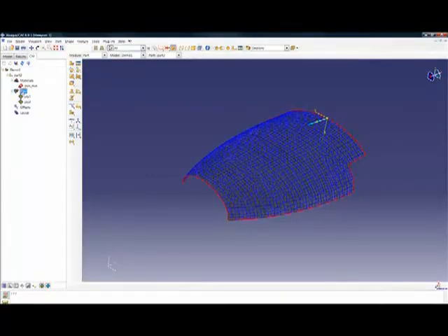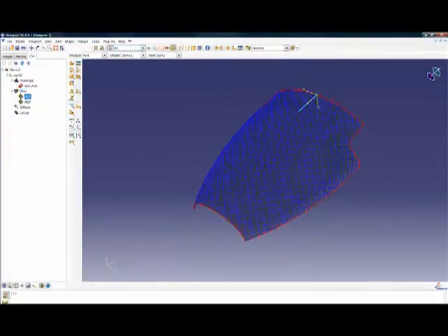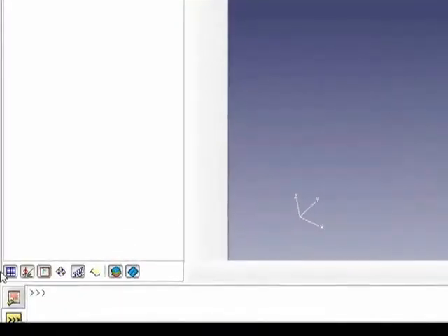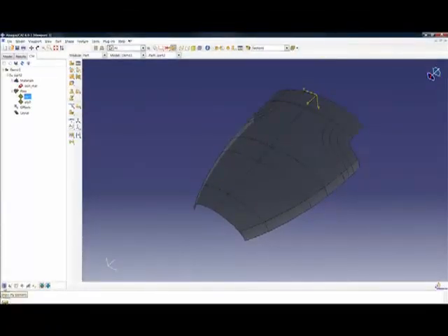And what we can then do is to look at those plies. We can verify what we want. We've got a number of visualization tools shown down here in the bottom left. So what we'll do is initially we'll just deselect all those, just to show the effects of them. So now, if you like, we have a blank image, and we're going to select ply 1, and we can show the elements that are covered by that ply.